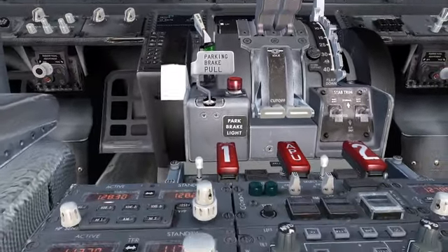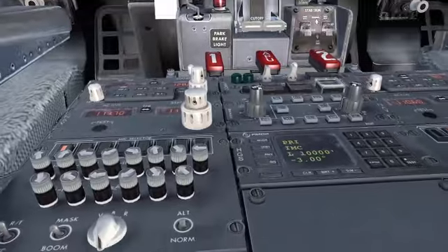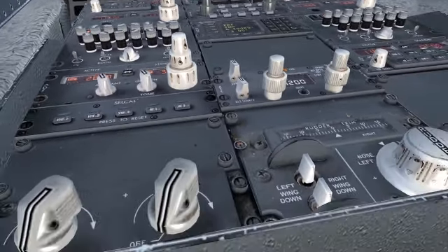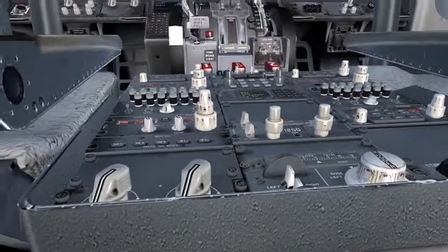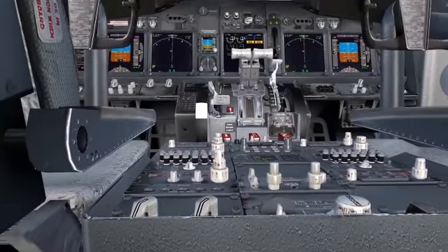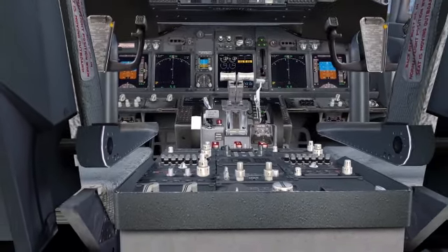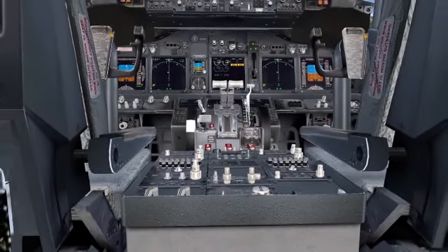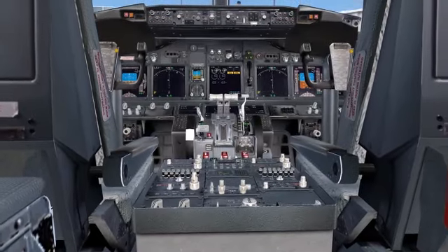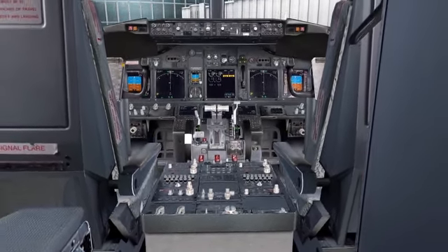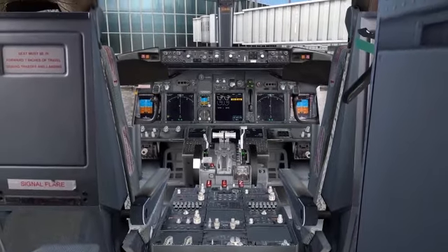Caution must be exercised when using the different sources of bleed air. During all operations of the pneumatic system, the wing body overheat and bleed trip-off light must be constantly monitored for malfunction. Any form of bleed air overpressure or overtemperature may break the pneumatic manifold apart. When in doubt, always adhere to standard operating procedures and the aircraft flight crew documentation.